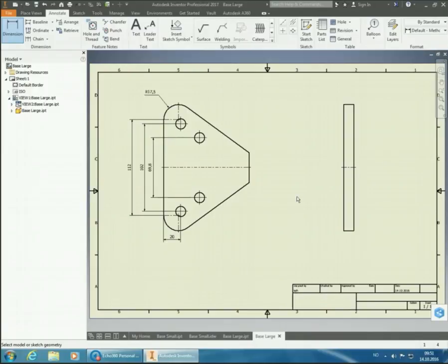So if we had put the length from the end here and to this center mark for the rounded edge, then we would have had to put that length in a parenthesis as a reference. Then we create the length for the next hole.